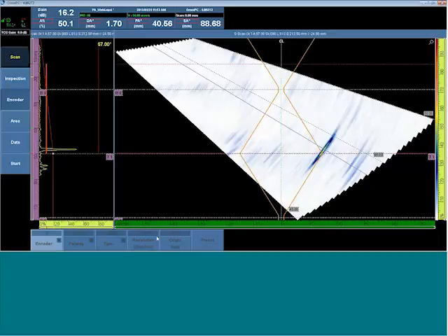We would normally always preset the encoder to 0 millimeters when the inspection starts. This allows us to also piece numerous welds together. If I were doing a 100-meter weld at 10-meter sections, I would be presetting file 2, 3, 4, etc. at 10 meters, 20 meters, 30 meters, etc.